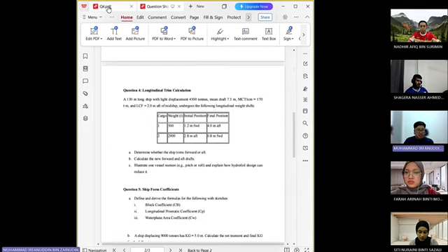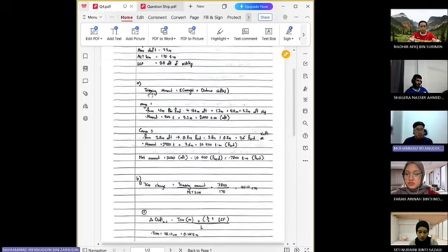Question A asks for the ship trims, which is with the formula trimming moments equals to the weight times the distance shifted. For cargo 1, the cargo shifted from 1.2 meters forward of the ship to 4 meters aft of the ship, equals to 1.2 meter plus 4 meters equals to 5.2 meters aft of the ship.